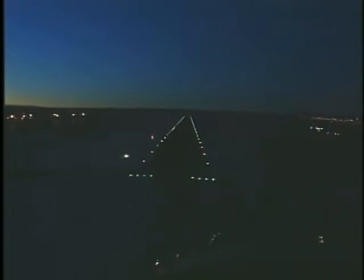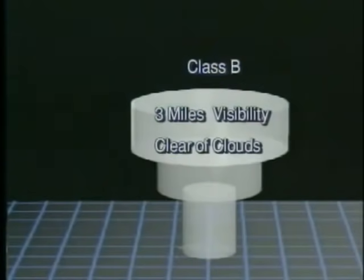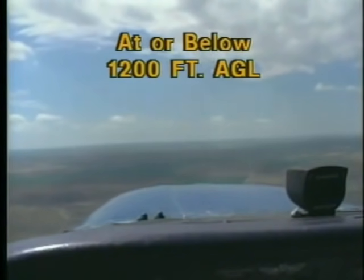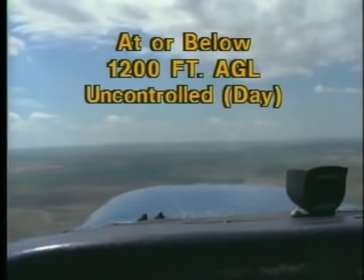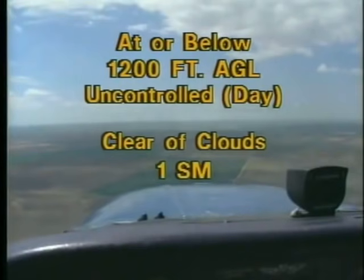However, in controlled airspace, you may operate an aircraft in an airport traffic pattern at night within 1/2 mile of the runway with a minimum visibility of 1 mile while remaining clear of clouds. You can also operate VFR in Class B airspace with 3 miles visibility and clear of clouds. At or below 1,200 feet AGL in Class G airspace during the day, you must remain clear of all clouds and maintain 1 statute mile visibility.